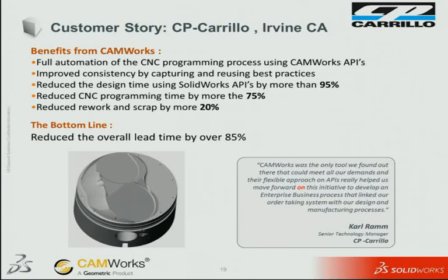You might have put fillets on the edges. You might have put fillets in the bottom of the pocket. But when CAMWorks looks at it using automatic feature recognition, it's going to see that kind of geometry as a pocket. Now, holes in SolidWorks, if you use Hole Wizard holes, just happen to be holes also in CAMWorks. So some features are similar between SolidWorks and CAMWorks, and some will be automatically recognized for manufacturing.